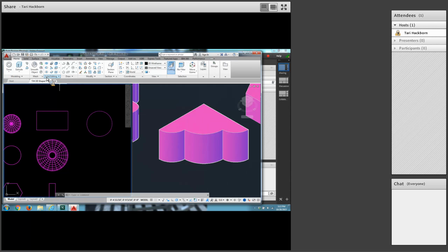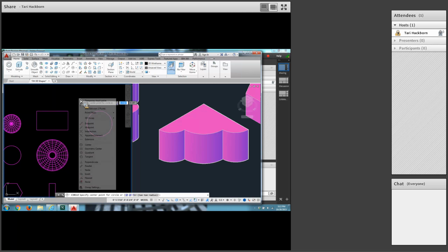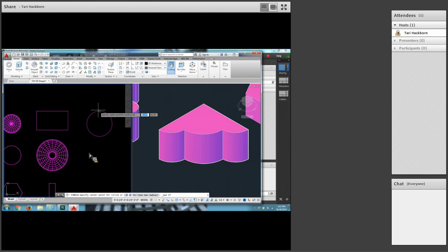Is it a radius circle also? Yeah. You could shift and right click and say I'm going to do it at the top quadrant of this circle. Either way. What radius does this one have? 1/8, it looks like. Then you're instructed to use the trim command, trim, and press enter, to trim out these parts so you can get that shape. There you go. Turn to page 58. They want you to use that edit polyline again. Don't do it. Go to the draw panel, get region.